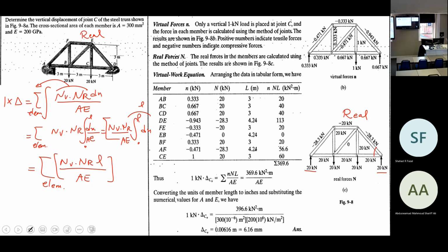Then move to the next node, and you will find the next two. If you reach a node with three unknowns, that's not good, so go from the other way. You just move node by node through the whole structure, writing the equilibrium equations for each node, and you will get all of the internal forces for the truss structure, right?